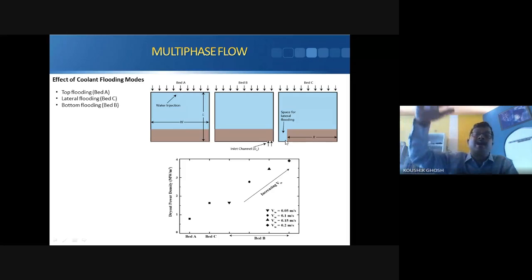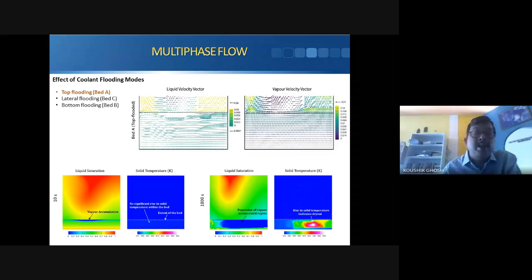Now, dryout is a safety parameter, something like the yield point stress used in material science or strength of materials. Dryout is the limit of the debris situation or the porous bed multi-phase situation. If you can increase the limit, you have a greater margin. So we have done this analysis to find which parameters can influence the dryout margin.